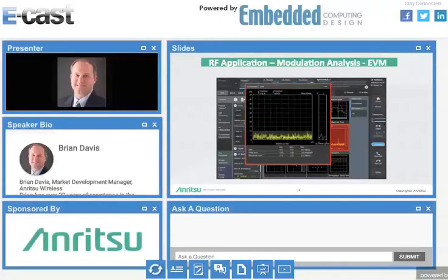Next, the EVM type measurements. So the next few measurements are all kind of related to each other. EVM is the difference between the ideal spectrum or the ideal received waveform and the measured waveform for allocated resource blocks. In this case, it's 50 resource blocks. So the average EVM is measured at 2 locations in time, high and low, with the high and low locations corresponding to the alignment of the fast Fourier window within the start and the end of the cyclic prefix. And it's presented as a percentage there in root mean square.